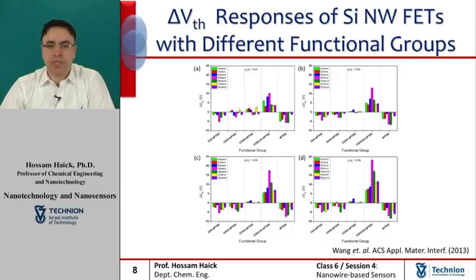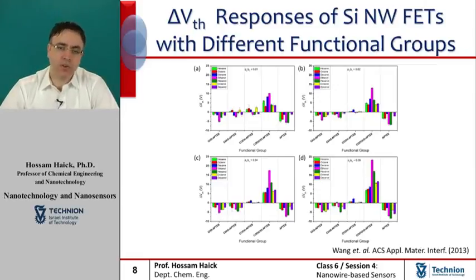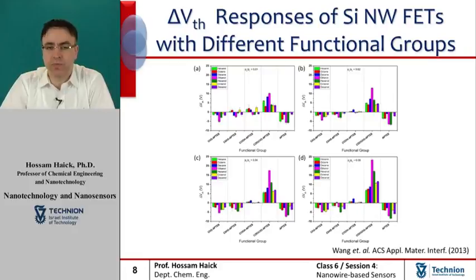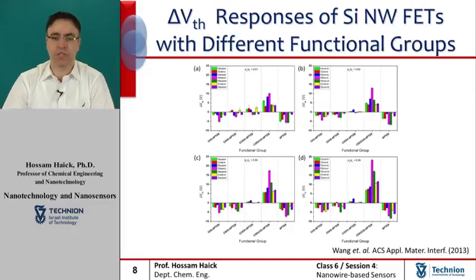As could be seen in the presented figures, the functional group types determine the voltage threshold shift direction. Upon exposure to VOCs, the voltage threshold of sensors with electron-donating functional group are shifted to the left side, namely they give negative response. In contrast, the voltage threshold of sensors with electron-withdrawing functional group are shifted to the right side, namely those which give positive response.